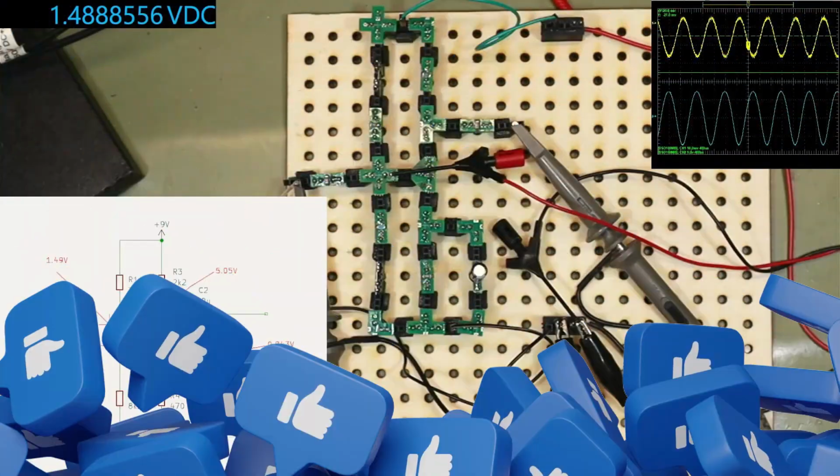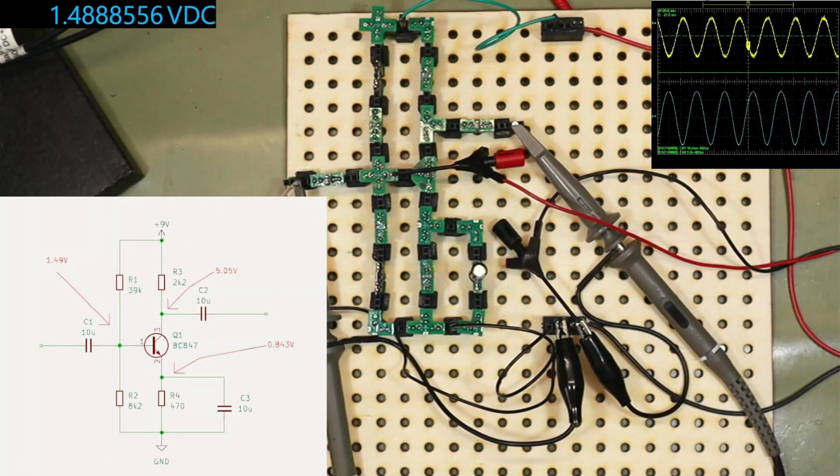Well, I thought I'd drop a different type of video on the common emitter amplifier, showing a few component faults and how they affect the operation of the amplifier, just to show what a simple fault can do and maybe make some fault finding a little bit easier. So I'll start with faults from A to H, just showing the DC conditions and what the input and output signals look like. And once we've looked at all the fault conditions, we will then in the final section work out what the fault is.